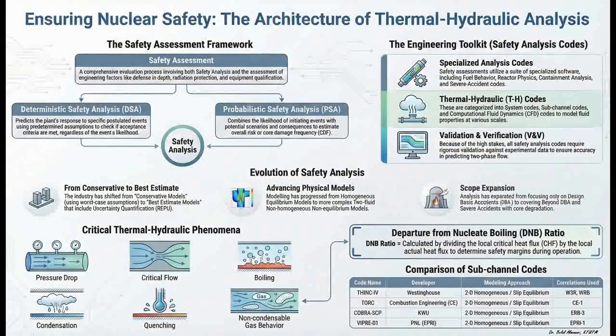The original work analyzed the Taylor instability of the vapor-liquid interface, but the modified Bromley correlation has to introduce an entirely new heat transfer mechanism. Thermal radiation. Exactly. At those extreme temperatures, the metal is so hot it is radiating thermal energy directly across the vapor gap into the surrounding liquid. The code has to actively calculate that radiative heat transfer, which is a massive computational pivot from the convective models used just seconds earlier in the simulation timeline.